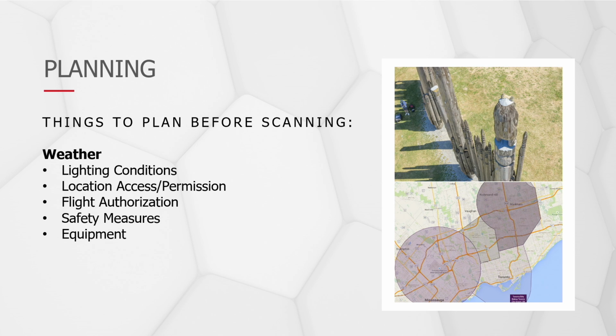Okay, so the first step, planning. What goes into planning a mission like this? Yeah, planning is so important. This is probably the most time-consuming step. Your planning involves checking the weather. So really, you want to fly photogrammetry on an overcast day where there are no harsh shadows on the ground.